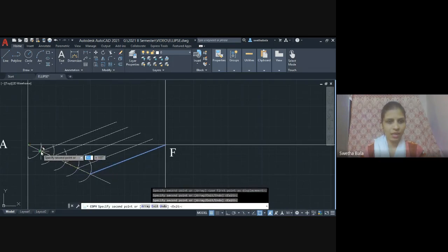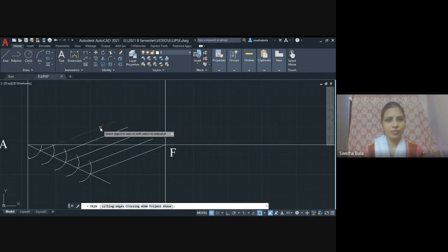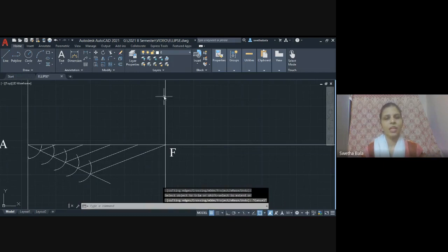copy selection using this, and move this to the different base points. I just need the parallel lines. So I have drawn the parallel lines. Okay. Now this is divided into 5 equal parts. So VF, according to the question, eccentricity is equal to 2 by 3. So what am I taking? I am taking V at the second part from F.